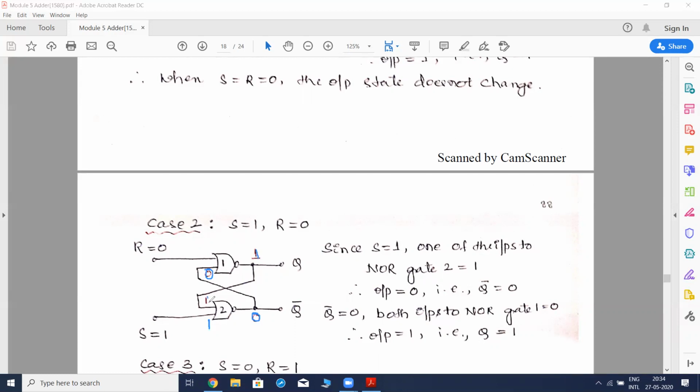So that same 1 comes over here. So it is cycling. So when both the inputs are 1, 1, obviously the output is 0. This is how we need to analyze. That means when we give S equal to 1, we are getting Q equal to 1. That means it is the set state.